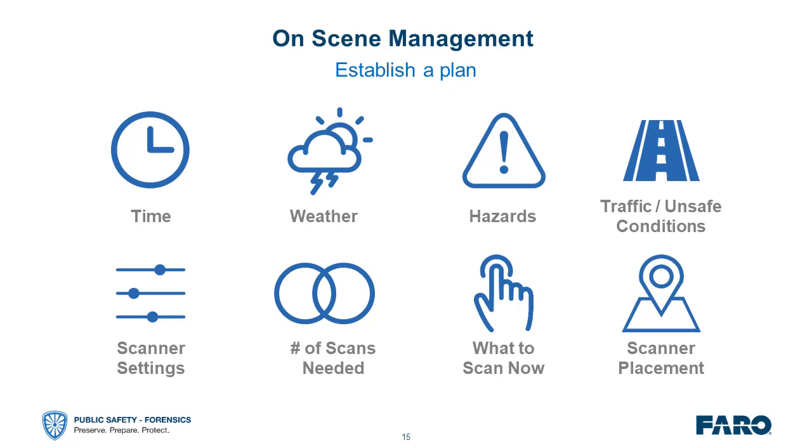A couple of techniques, and then what to scan now. And that "what to scan now" note applies to, well, do I really need to do all of the scans right now while I'm at my site? Can I return later at a time when the traffic is not as bad? Or maybe fill in some dead spots in an area or something along those lines, right? But that sidewalk's still going to be there tomorrow. Correct. That scuff mark may not be. That's correct. So that's all part of a well laid out, established routine to capture the stuff that may not